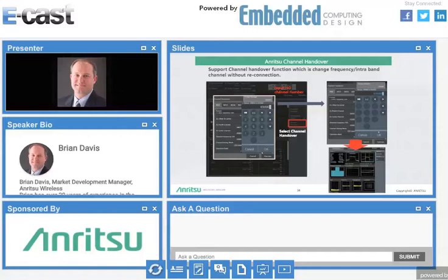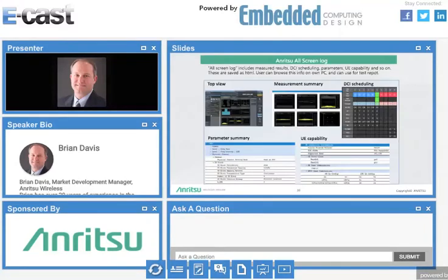Here's channel handover. Again, this is very intuitive. If you're on a channel and you want to change to another channel, do a handover. You simply go to the channel input area, put in the channel you want to hand over to, say OK, boom, you get an RRC reconfiguration message. You're doing a handover immediately while you're in a call, and you can go forward and take measurements on that new channel or band. We don't make you end the call, change the parameters, and then bring the call up. That's the real hassle.